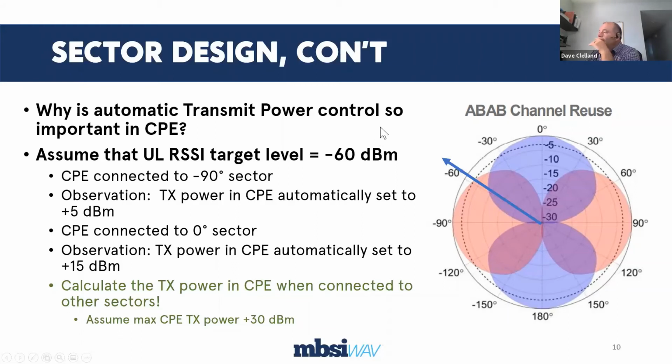So why is that? Let's use the west sector again as my example. If I have a CPE that's in very close and I have a small amount of path loss, maybe only 70 dB instead of 104 like it would be at a kilometer, my receiver receives this really strong signal from a close CPE and then a weaker signal from a CPE farther away, and maybe an even weaker signal from a CPE farther than that.